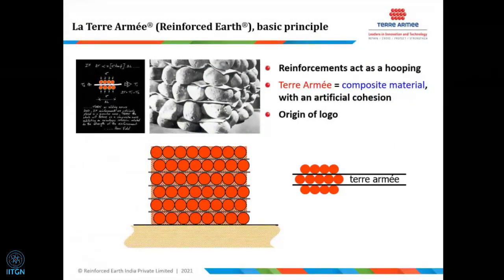The logo that came up, what you see, is basically the soil particles. And the concept of soil reinforcement is well explained in the picture. On the top middle picture, you can see the stones which are very rounded, and this vertical structure was built using this board. It's a small board, and the friction between the boulders allowed it to stand vertically. Now, sometimes I have been asked how this concept applies to soil. With boulders it is very well understood, but I think the concept is very well applicable for soil as well.